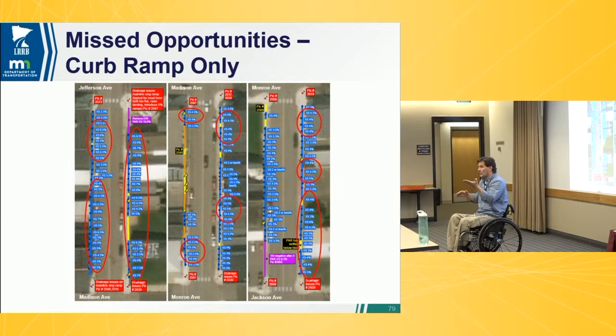You've got to raise the curb line if you want to fix the cross slopes. So the next year, you rip out all the curb, come in with a paver again, heat it up, and let's go. Do you rip out the curb and do a road diet and move the drainage structures while you're at it and patch into them? No. I mean, none of these are good options.